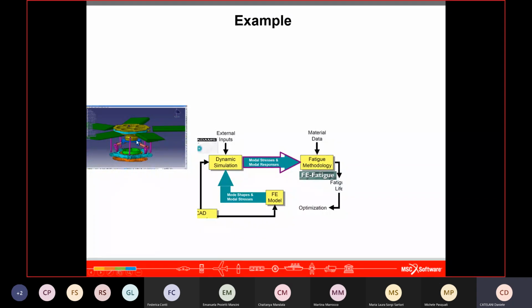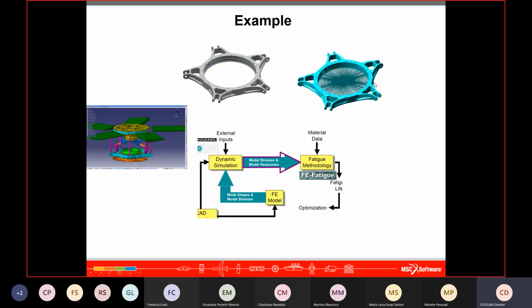So you can use a CAD model in which the designer starts to provide a preliminary definition of the geometry and the assembly of the system. From this preliminary definition, this component is transferred to the finite element user. The structural guy is able to perform all the structural evaluation, and he can export the flexible body for Adams.